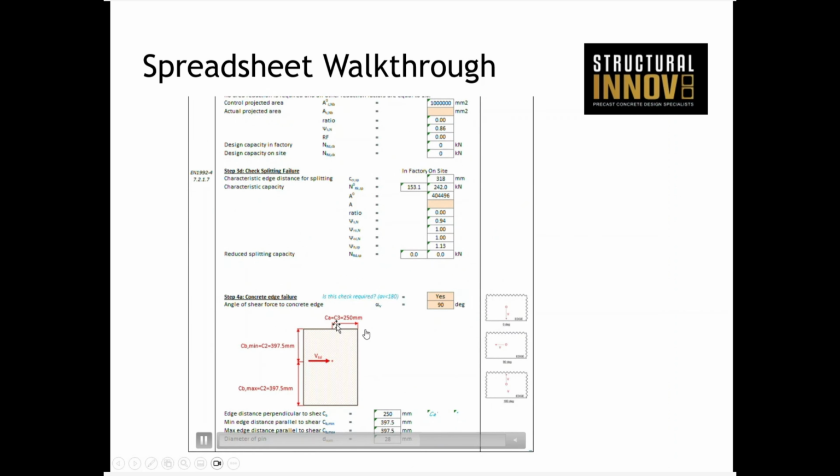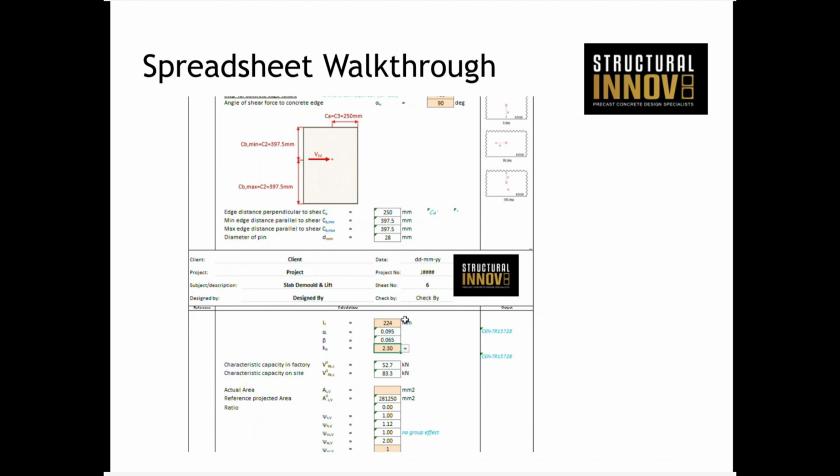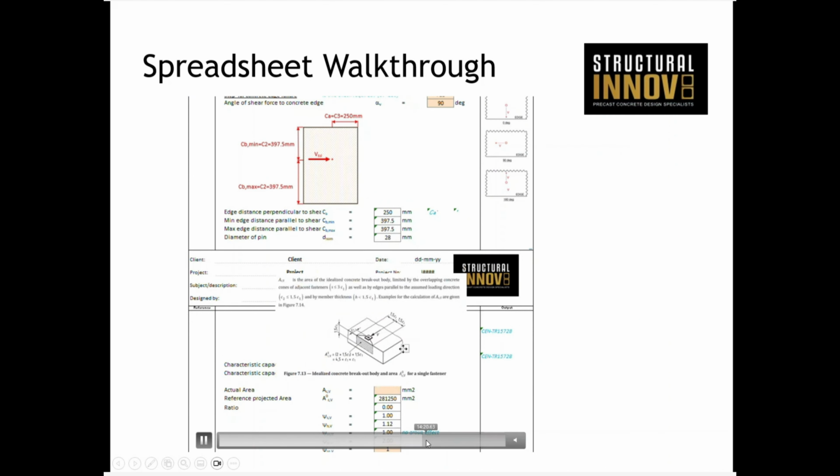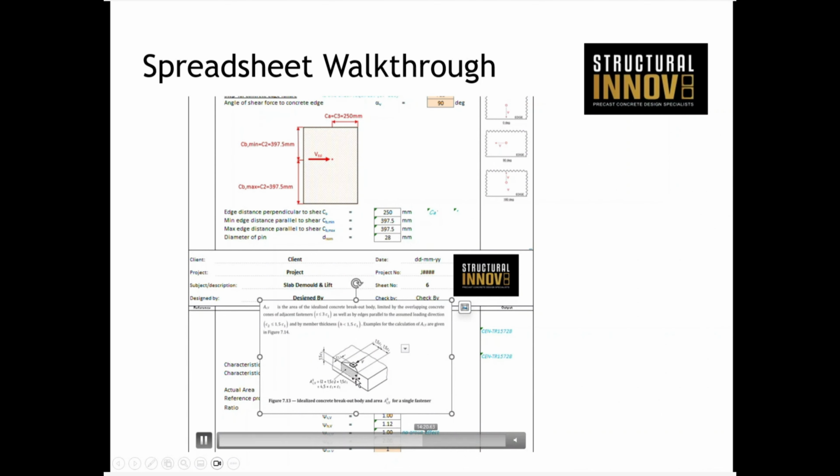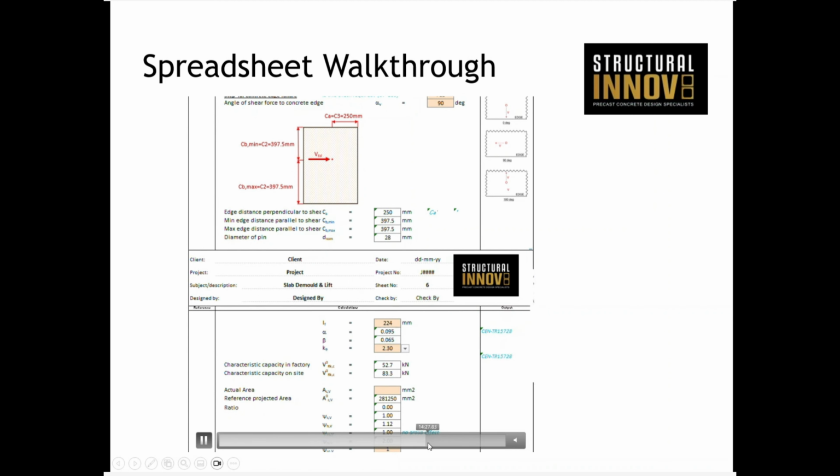So again, you need to ensure that you can achieve 1.5 times that distance, left, right, and down into the panel. So when you work out your calculations, this is the kind of diagram form that we're using. 1.5 times 250 is 375, and we do have that in this particular case to the left and right, but we don't have it in the thickness.